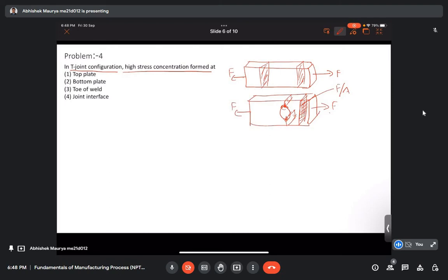But here the nominal stress value will be given by another area, we are calling it A, so this plus this, and since this area is smaller, the stress value will be higher here, and the probability of the component failing will be higher at these points. So these are the points of stress concentration, and this happens because of the geometry of the body.